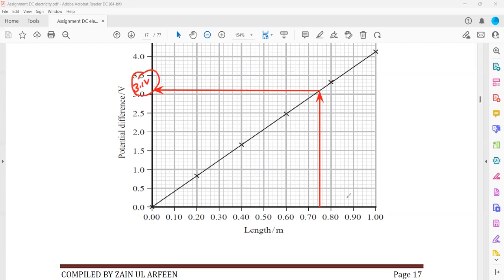volts. So we have the voltage 3.1 and we need the power. So P is equal to VI. So 3.1 multiplied by 0.2, because we maintain the current in each case at 0.2. When we multiply them, we'll get a power of 0.62 watts. That's the power dissipated. So using the length, we work out how much voltage, and voltage multiplied by current will give the power.